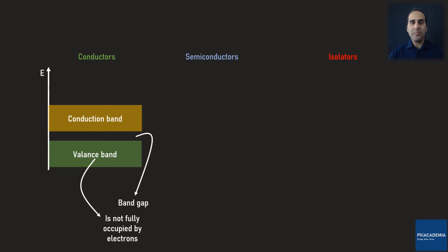As a result, a number of holes or states remain unoccupied. There are two charge carriers, electrons and holes. Both are causes of electrical conductivity. As a result, a not fully occupied valence band causes a material to behave as a conductor. Later in this lecture, I'll discuss the charge carriers, electrons and holes, in more detail.